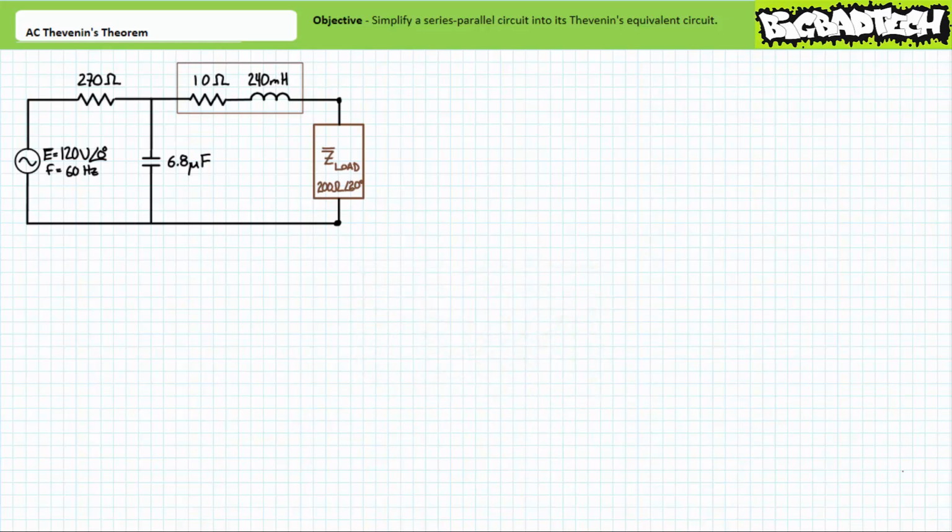If you recall, Thevenin's theorem as applied to DC circuits rendered even the most tangled and gnarly of series parallel circuits into tame and docile pure series circuits that sit, stay, and roll over on command. The same is true for AC circuits, the one complication being that phasor equivalents and complex impedances are employed for analysis purposes.